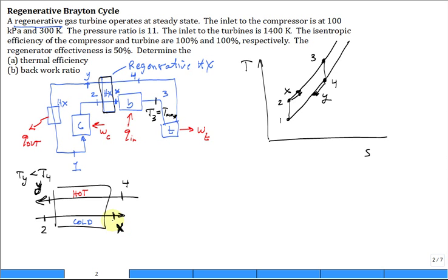A lot of times they'll plot on a temperature scale, from one side of the heat exchanger to the other side. They'll show the cold fluid heating up, going from T2 to TX, and the hot fluid coming down. Because they have the same mass flow rate, assuming constant specific heats, the slopes of those lines would be exactly the same. They'd be parallel lines. And then this would be T4, and this would be TY.